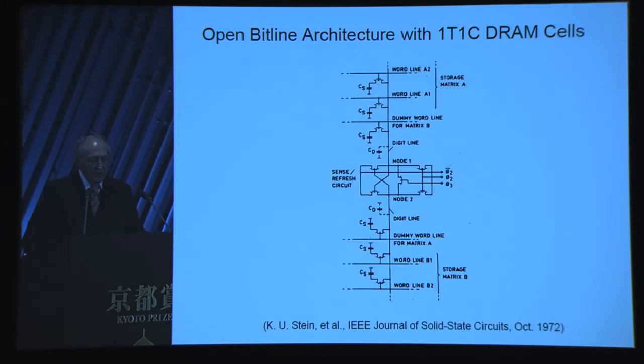And those levels are fed right back onto the bit lines where they're written into the memory cells to restore the original levels. This seems to me to be one of the most fortuitously efficient circuits ever devised. As far as I know, the balanced latch has been used in one form or another in all one-transistor dynamic RAM chips after the first 4 kilobit chips. There have been many improvements and variations.